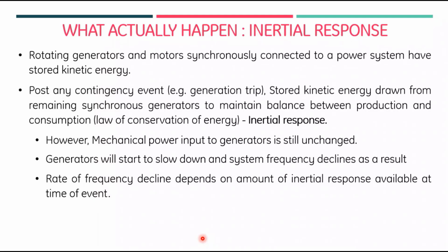The turbine has a significant amount of mass, and it is running at, let us say, 1500 rpm. So it has this angular speed of 1500 rpm, and then it has its own mass. Then we know the half J omega squared is the kinetic energy stored in the combined turbine and generator system. Now it is not producing any energy. It is just consuming energy to run at 1500 rpm first.